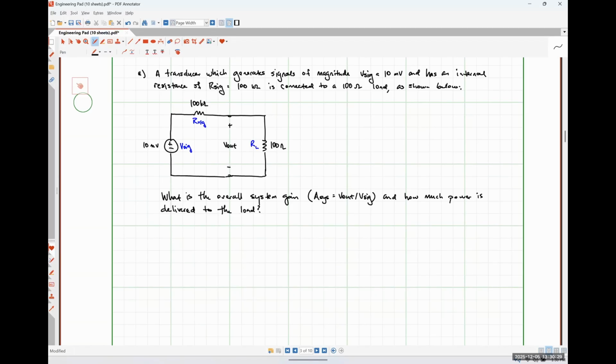possibly a piezoelectric sensor, like would be used to maybe measure a person's heartbeat or something like that. Typically speaking, a piezoelectric sensor does a pretty good job of generating voltages and an absolutely poor job of being able to generate current. So it isn't capable of producing a lot of power overall. It's just really good at making relatively large voltages.